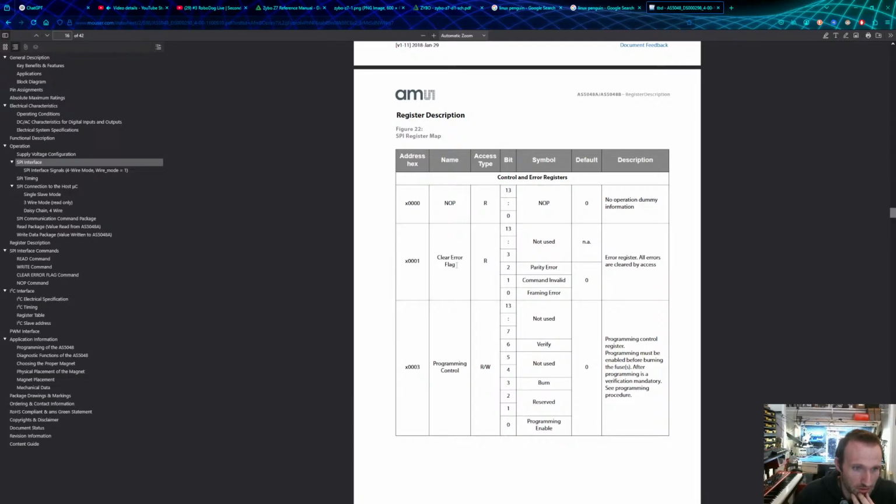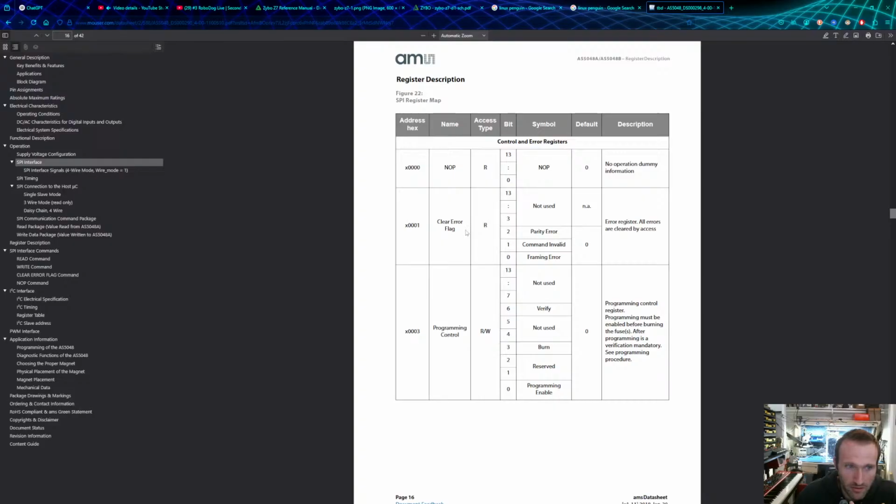Okay, so what this tells me is that in this register table in this microcontroller, there's probably some error flags, and just the act of reading them clears them. And again, these transactions are happening over SPI. When I want to send a SPI packet, this doesn't tell me what the structure of the SPI packet should look like, which I need to find because I need to understand how to construct it. These are just, assuming you have a proper SPI packet constructed, the registers that you're accessing. So if you choose to read this register, you will clear error flags.